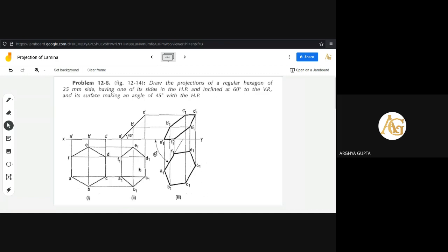Now with the pencil compass, take the measurement between F1 and D1 and mark the point here. Also take the measurement of A1 and C1 and mark the point here. Okay, so that's how D1 and C1 are marked. So we have marked only 2 points. Now what you have to do, so this line is equal to this line here, isn't it?